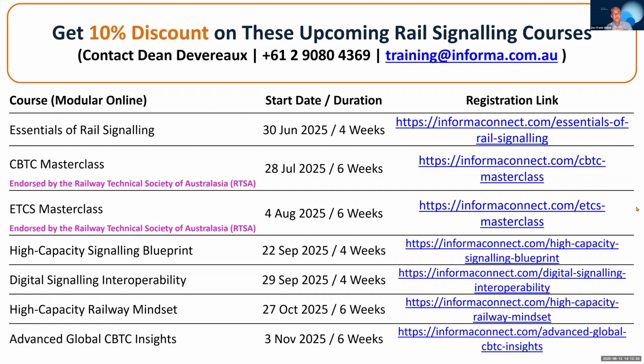The alternative for CBTC is LTE or 4G radio. That's the standard radio system used for CBTC in China, for example. And it will also be used here in Perth for the CBTC application here. For ETCS, traditionally, it was a system called GSM-R, which from a telecommunications perspective is Stone Age. Yeah, it was modern in the mid 1990s, but we are now 30 years further down the line. And 30 years in the telecommunications industry is an eternity.